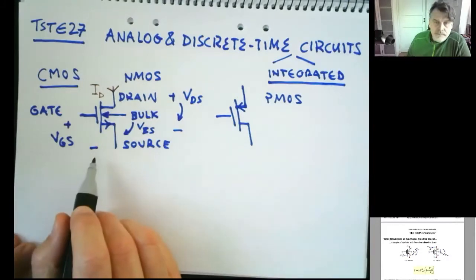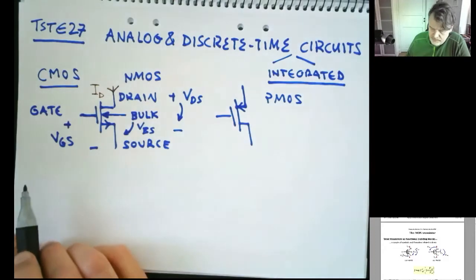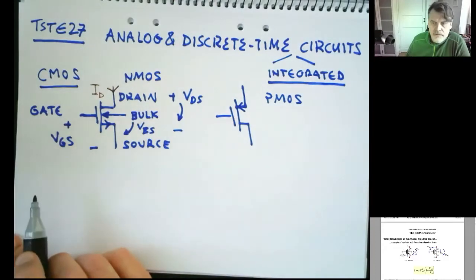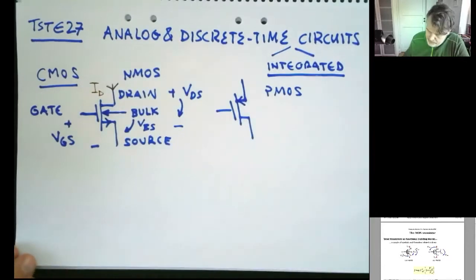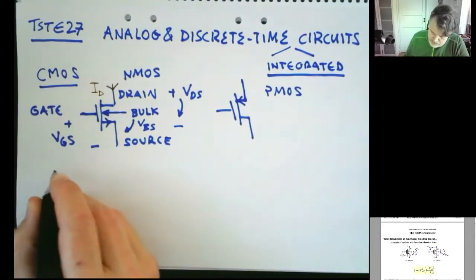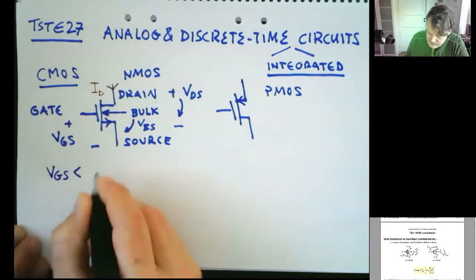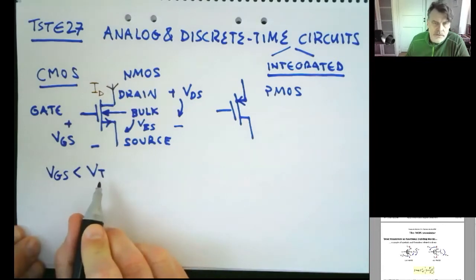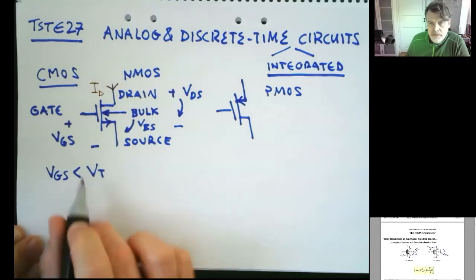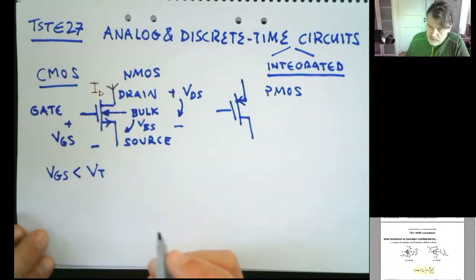Then what happens here for the transistor? Well, dependent on the voltages and the currents through the transistors, it has different operating regions. So just recapitulate those. We typically say that if VGS is less than VT, a threshold voltage, which is typically related to the material, so for silicon, you might recognize this 0.7 volt threshold.